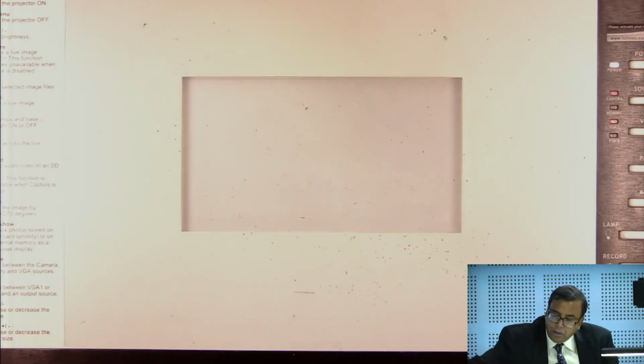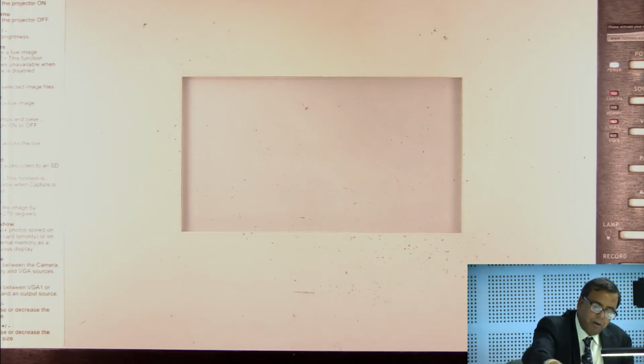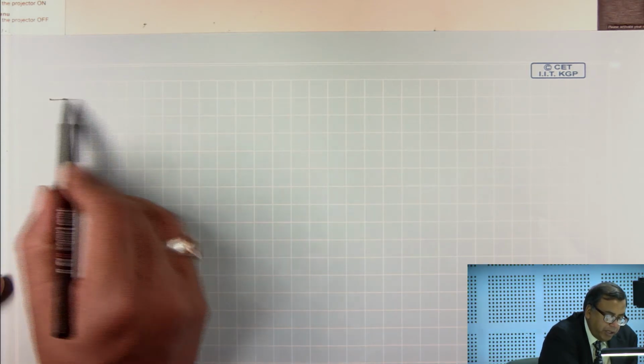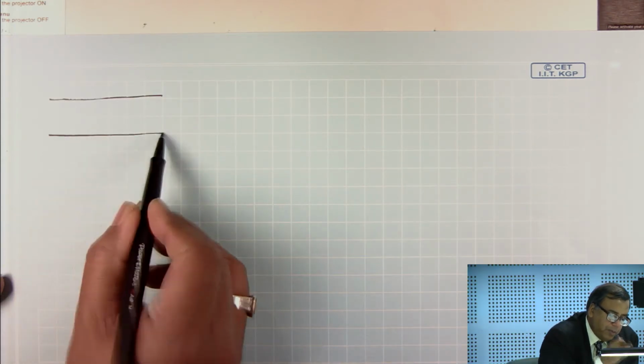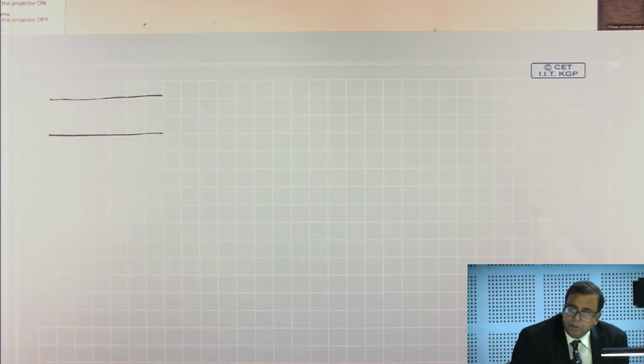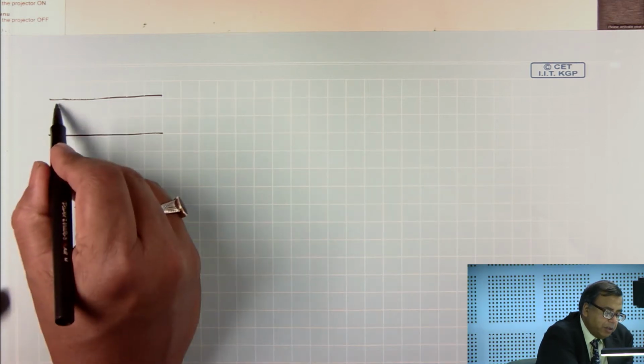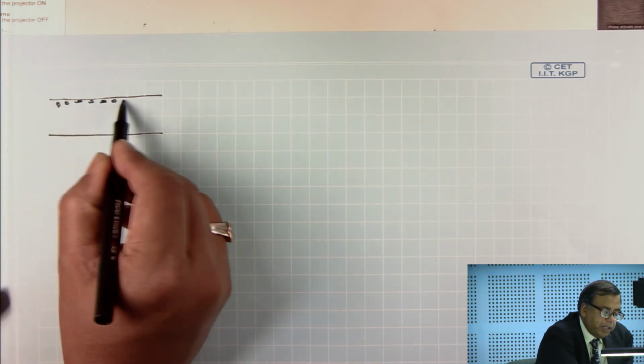now let us look at horizontal flow, horizontal adiabatic two phase flow. So, in horizontal adiabatic two phase flow, things are not uniformly distributed. Okay. Even if you have bubbly flow, the bulk of the bubbles will tend to stick to the top.